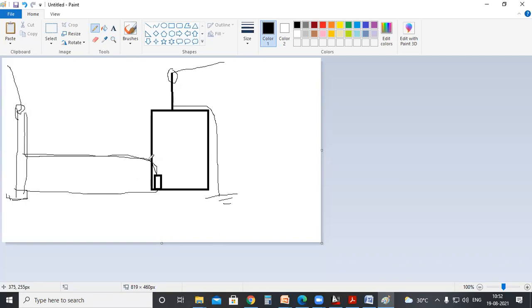This can carry the surge within a short duration, like 3 seconds, 1 second. Even if your building equipments are not turned on, this may cause an arcing current. Even if it is isolated, there's a chance to get the surge current to the connected equipments. If the equipment is connected and turned off, this contact might be enough for the arcing current to pass into the building and damage the equipment, especially low voltage devices.